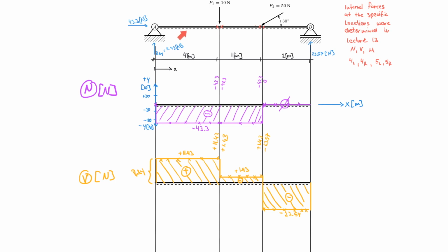So we can understand that every force that acts perpendicular to the beam, like the 10 and the vertical component here, have to have an influence on the shear force diagram. And you see it here, RAY. How big is this jump here? That jump is exactly the force of 10 newtons here on the top, right? So that jump is 10. So this is 10. This is just for education. Nobody would write this later on, right? But I want you to see that we have a jump of 10 here.